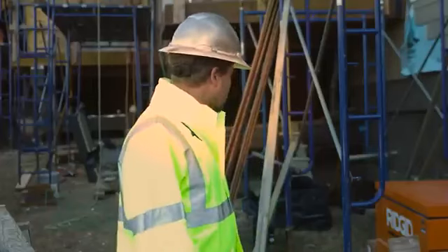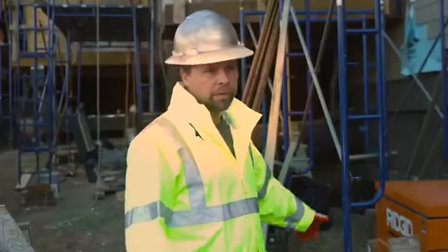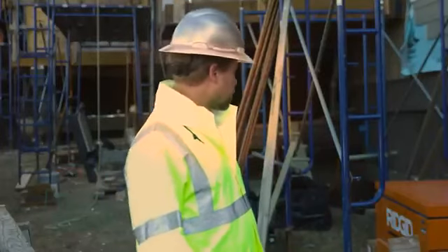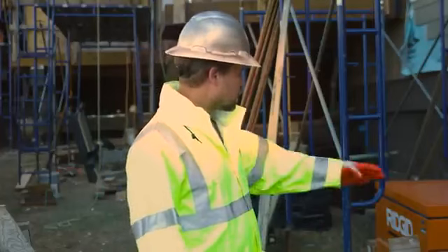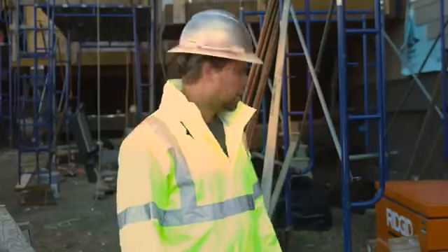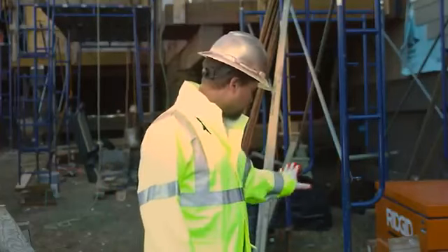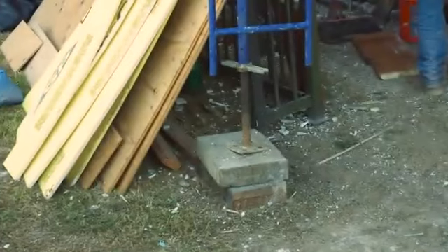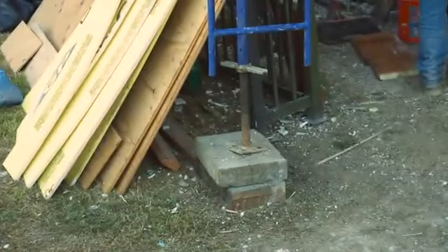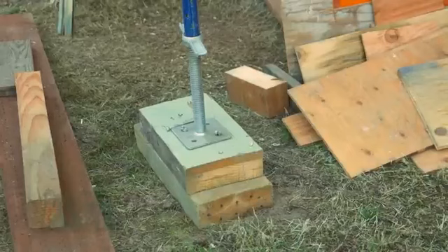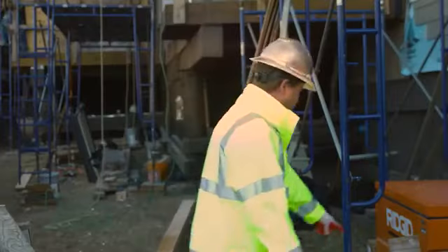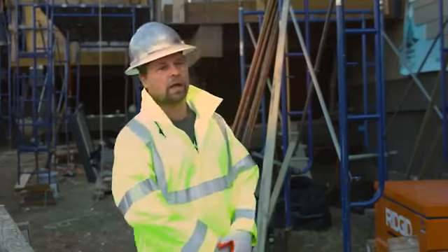Well, obviously it starts from the ground up, so I want to make sure that the surface is properly prepared. There are some uneven surfaces, so I want to level it out, or do some digging to stabilize it. We want a solid base because we don't want something to be depressed in the ground later on, since obviously the rainy season is coming. So what we have now might be different later on. I want to have a pretty wide base underneath the scaffolding.